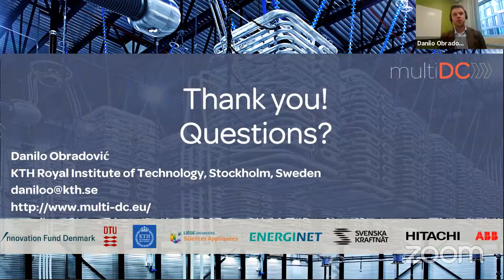So far we were looking into only one side droop, so we're only interested in the needs of the Nordic power system. However, we've seen in the research work that it's totally acceptable to set the droop on both sides. There have been some concerns about whether this would work properly. I think the power output will be slightly different, but I didn't see that it would cause any kind of issues or stability problems if you have it on both sides. It's just that TSOs have to coordinate what exactly the values will be, as we saw in Robert's slides, in terms of capacities and droops.